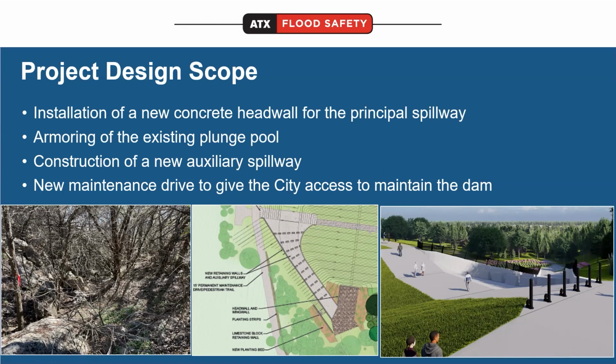It's going to be wider and it's going to be made out of concrete. And these blocks that you see, those are called baffle blocks, which allow for some of the energy that the water would bring to dissipate. So we don't have significant erosion downstream. And basically, it's being redesigned so that it can pass the required flood for safety purposes.